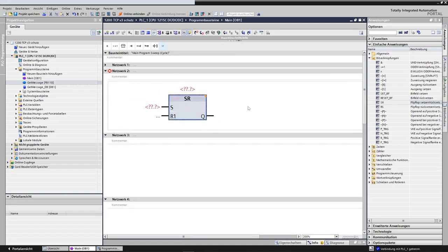However, we need to consider a few things. We can select its related blocks in the upper right corner of this block, namely the RS. That means if I made a mistake and a wiring of this block has already occurred, like here an assignment, some inputs, here an output, or a marker, or a variable of mine, and when everything is switched, I eventually notice that this block is not the right one, but I would like the SR instead, then I can quickly swap it like this.